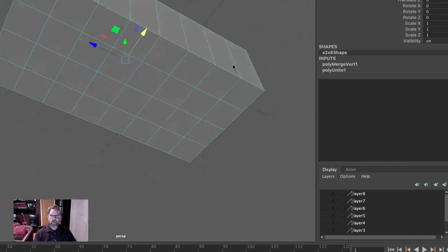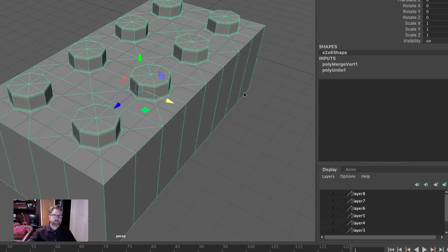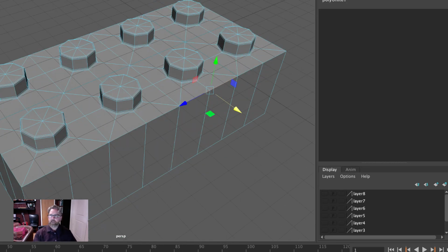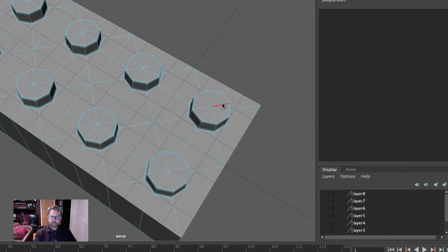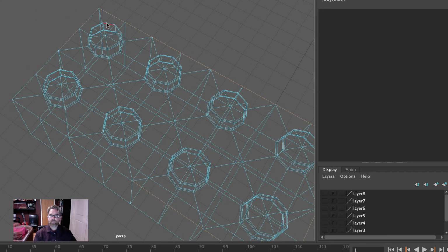So this is going to be one without a recess. So this would be one, if it was across and we weren't going to see the bottom, this is the piece we would use. Now selecting these edges is going to be a little bit of a chore, because on this top piece we have to go all the way around, and maybe it's easier in the 4 view to see. So I'm just shift selecting all the way around, getting the top rectangle.